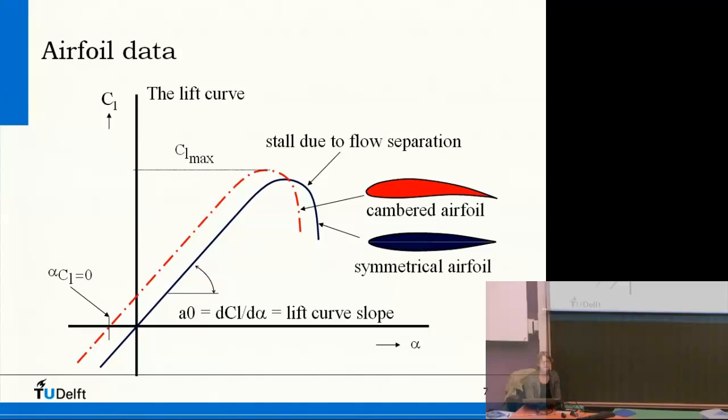So this is a symmetric airfoil, and how can you see this is symmetric? Any idea? Yes? Exactly, it passes through 0. So at 0 angle of attack, nothing's really happening. At 0 angle of attack, the flow passes on top, on bottom. Afterwards, the flow is still horizontal, so a force has not been applied to the flow, so no force from the flow on the airfoil, so no lift. Of course, if you have a cambered airfoil, like this, at 0 angle of attack, the mean camber line still has an angle.